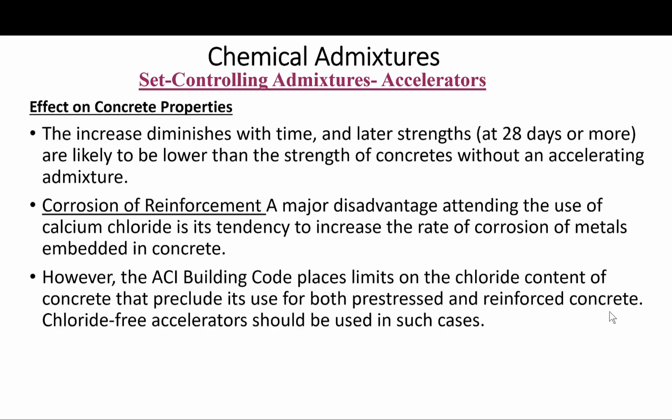Also, accelerating admixtures are said to increase the drying shrinkage and creep. But as I mentioned in the previous discussions, as with retarders, it is the rate of deformation rather than the ultimate value that is affected. And again, I will not pass judgment completely, it's still out there, it has to be investigated. But the early shrinkage leads to high tensile stresses in restrained concrete, resulting in increased cracking. So again, you have many variables that have to be investigated.